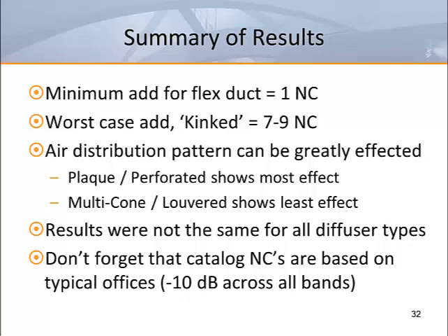Certain diffusers are more susceptible to inlet condition effects due to their design. Typically, a plaque or perforated diffuser would have the most issues, while multi-cone or louvered diffusers would have the least. That's because the cones or louvers tend to better redistribute the air downstream from a poor inlet condition. Plaque diffusers can't do this, so proper inlet conditions are absolutely necessary to achieving the high performance that these diffusers are known for. And don't forget that the catalog NC values are based on a 10 dB across-the-board deduction that may not reflect your actual job site conditions.